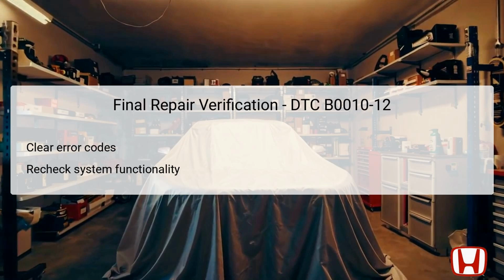This verification step ensures that the repairs made have resolved the underlying issue. It's also a good practice to run a second diagnostic check to affirm that no new codes appear, indicating that the SRS has returned to normal operation. Proper verification is essential to ensure that the airbag system is now functioning as intended, ready to provide protection in